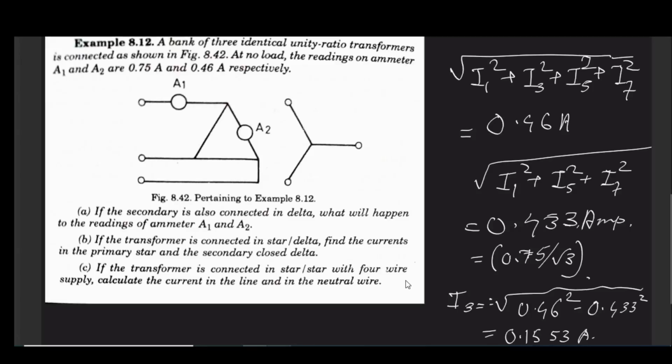So in that case, I would like to request you think about it is not only the MMF but the flux that actually control your EMF production. So primary and third harmonic together produce the total flux, and that flux will interlink with your secondary side winding.